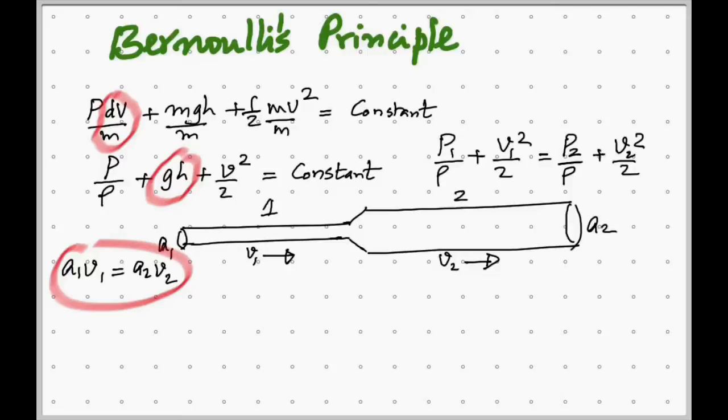Did that make sense? And then, what pressure is this? Is this the absolute pressure or the gauge pressure? No, it's the absolute pressure. So write that down there. In Bernoulli's principle, whatever you see is the absolute pressure. So if you are asked to find the gauge pressure, there's no other way than to first find the absolute pressure and then subtract the atmospheric pressure. So that's why you had difficulties on the Weber sign. Because you probably are thinking that this is the gauge pressure. No, it is not.